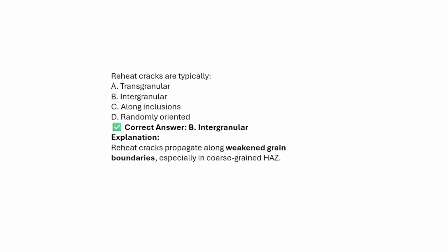Which cracking is that? Okay. Next, it is the intergranular cracking. The reheat cracking propagates along the weakened grain boundaries, especially in the coarse grain HAZ.